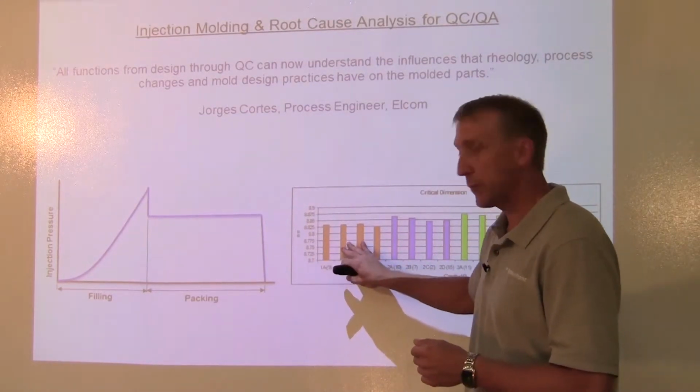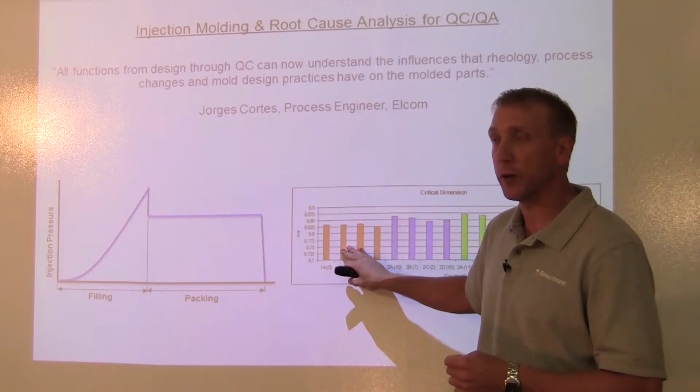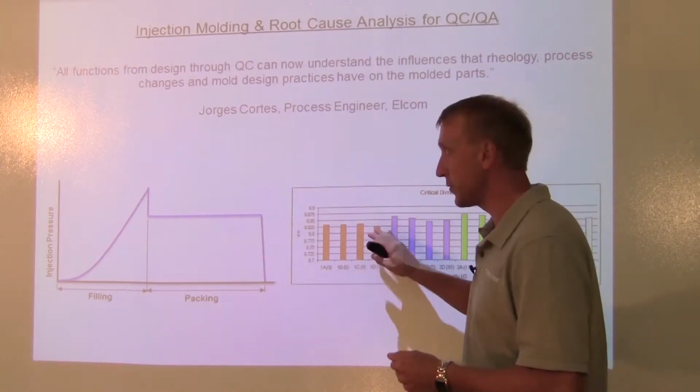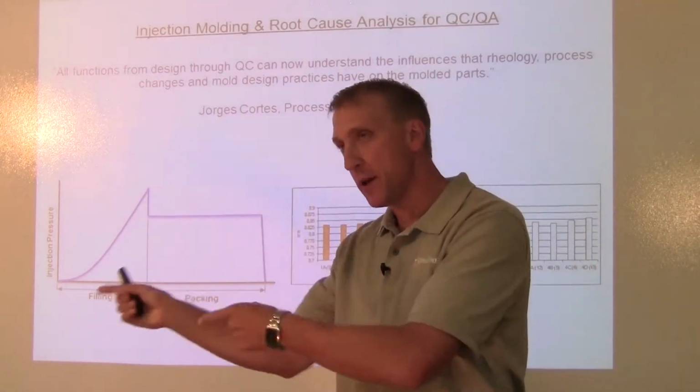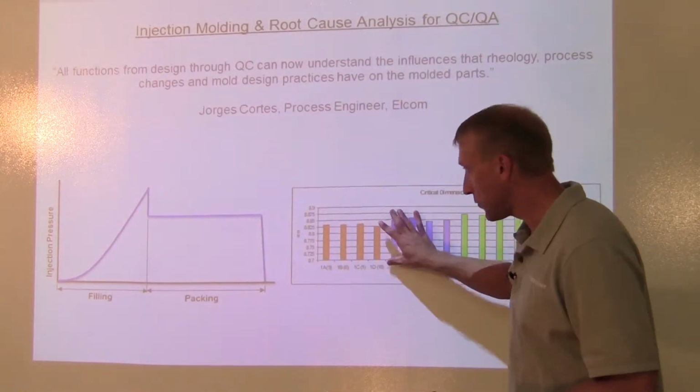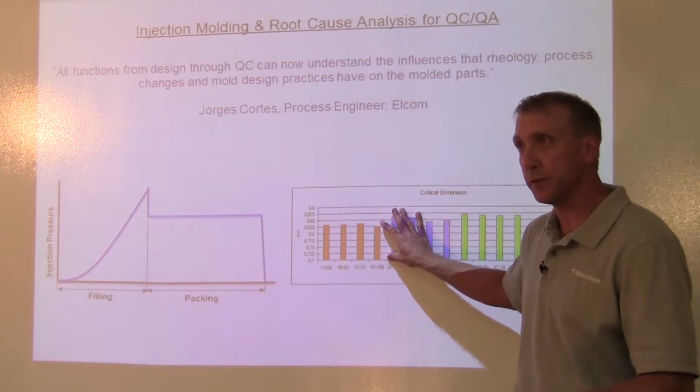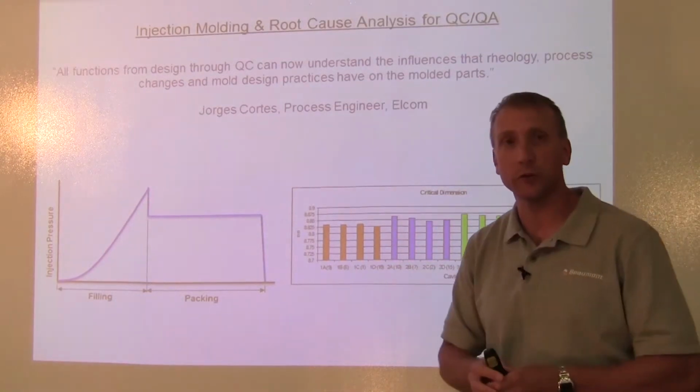Again, we're looking at it here from the plastics perspective, also incorporating our flow grouping diagnostics into this course as well, so that they can look at their part quality data, relate it back to the processor, who should also be looking at the data by flow grouping, and they can come to solutions quicker.